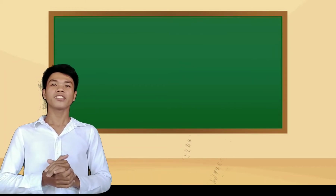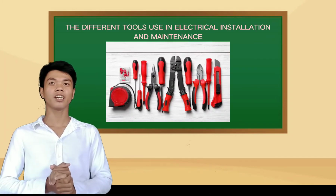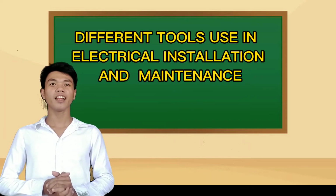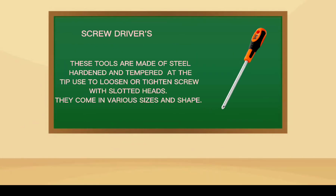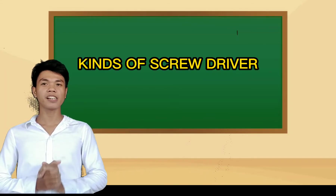And that is our lesson for today. The different tools used in electrical installation and maintenance. And here are the different tools used in electrical installation and maintenance. Number 1. Screwdrivers. These tools are made of steel, hardened and tempered at the tip, used to loosen or tighten screw with slotted heads. They come in various sizes and shape. And here are the different kinds of screwdrivers.